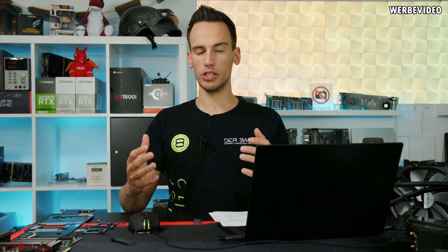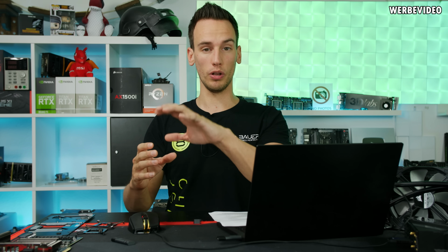In the semiconductor industry, you're trying to scale down things further and further. You try to make it smaller and smaller to pack more transistors on the same area to increase the performance. The only problem is if you decrease the size of the gate, if you make it even smaller, you have something which is called sub-threshold leakage. And this describes a phenomenon where electrons can flow from source to drain even though there is no voltage directly attached to the gate, and this is causing a lot of leakage with the CPUs.